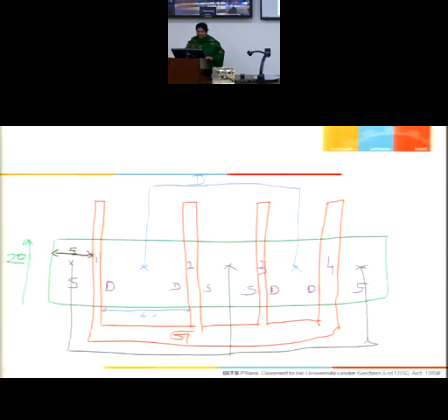So total drain junction area is 6 lambda into 20 lambda, that is 120 lambda square, into Cj area. Remember, this is how we compute capacitances. Parasitic capacitances: C drain to bulk plus C side wall.